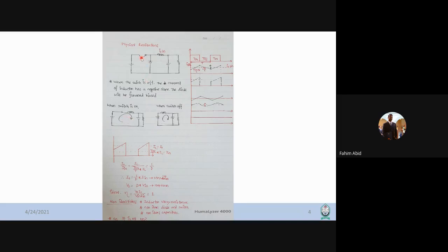And in the second case, when the transistor is off, during T off when there is no gate signal, the transistor is no longer conducting current. So the left part is open and the diode is now forward biased, and the circuit looks like this.